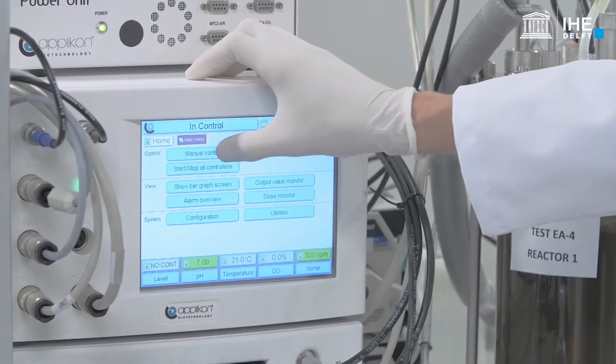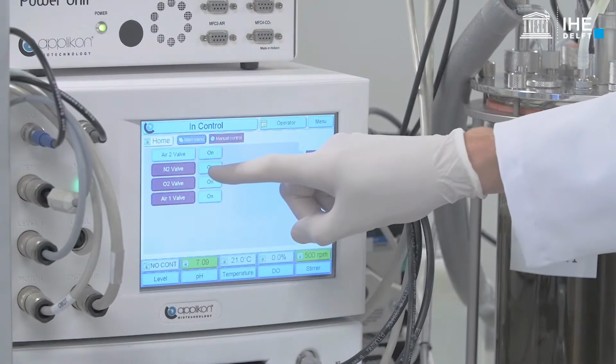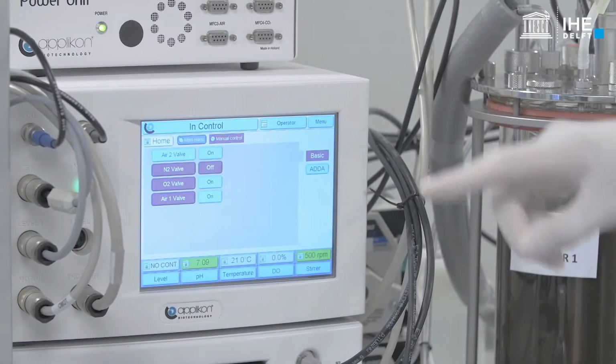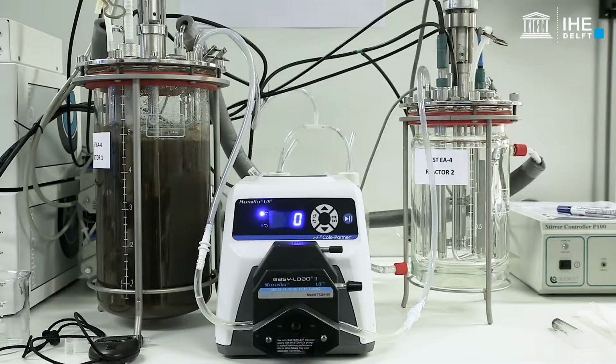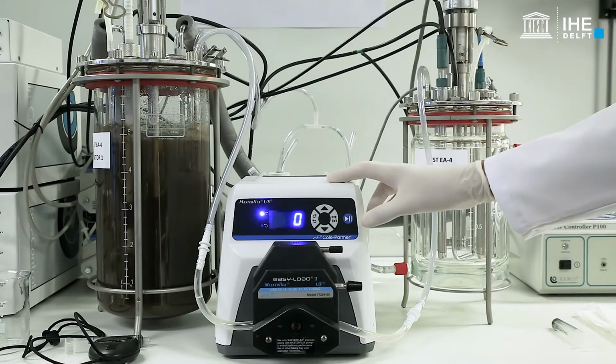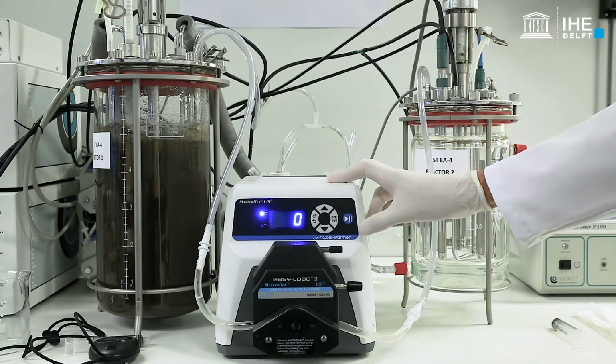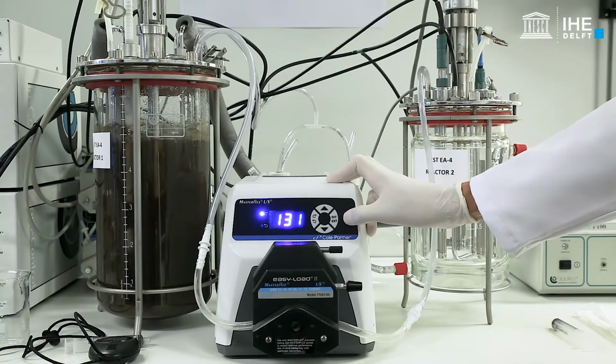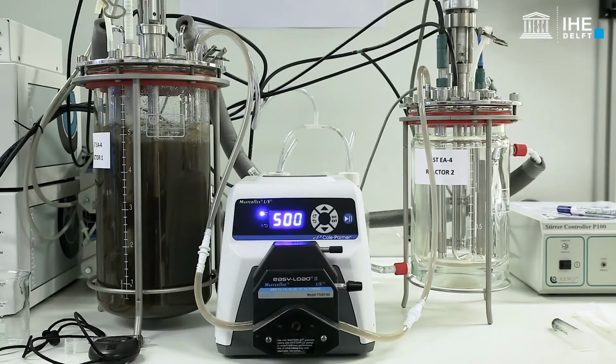After the anaerobic stage, restart the supply of nitrogen gas to reactor 1 and also supply nitrogen gas to reactor 2 to create anaerobic conditions. Thereafter, transfer the sludge from reactor 1 to reactor 2. During the sludge transfer, do not turn on the stirrer. Avoid mixing the sludge and keep the supply of nitrogen gas. This will minimise the intrusion of oxygen and will also help to maintain the sludge under anaerobic conditions.